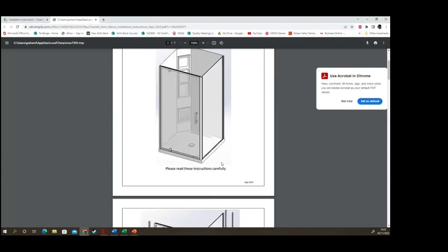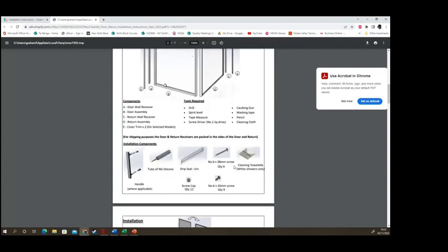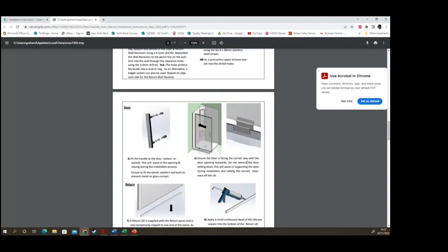Yeah. You're relying on the builder to do it. He might forget it, or he might put it halfway up and think you didn't need one at the top. And guaranteed, if you don't do it, it won't be in the right place. And the other thing is, don't be mean. If you've got the timber there, just put an extra. If you've got to double up the studs for where you're going to do your fixing, at least then you're not going to miss it.